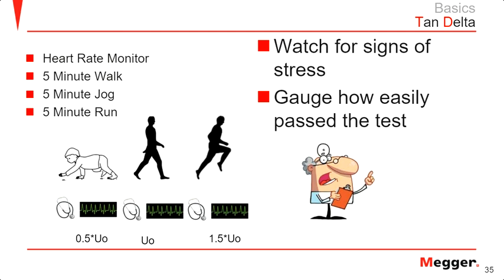Okay, so if we stop the test when we find the cable is weaker, do you get more time to procure and replace the cable? So a tan delta test is usually done during a maintenance or an acceptance test. So yes, that allows you to.